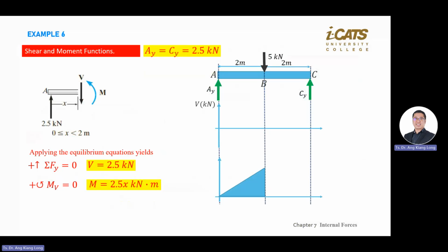It's important to write the shear force plus the unit. On the top is the shear diagram, on the bottom is the bending diagram. So you draw the Y and X axes. Here is M versus X. Your X is in brackets, meter, because the question is in meter units. This is the general draft that you need to prepare before you go into the shape of the graph.